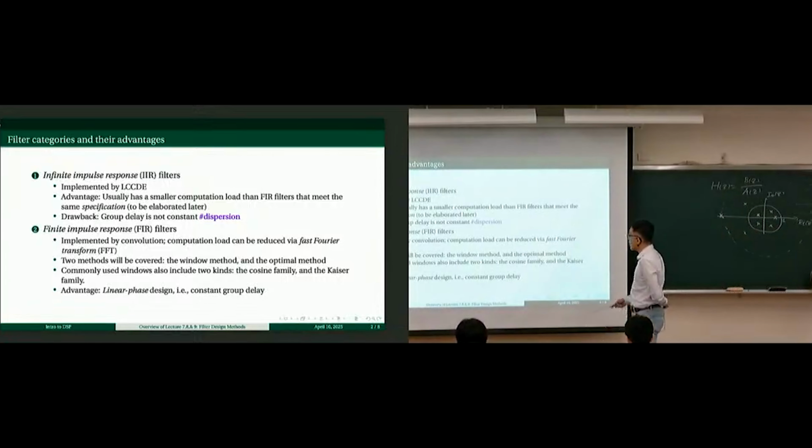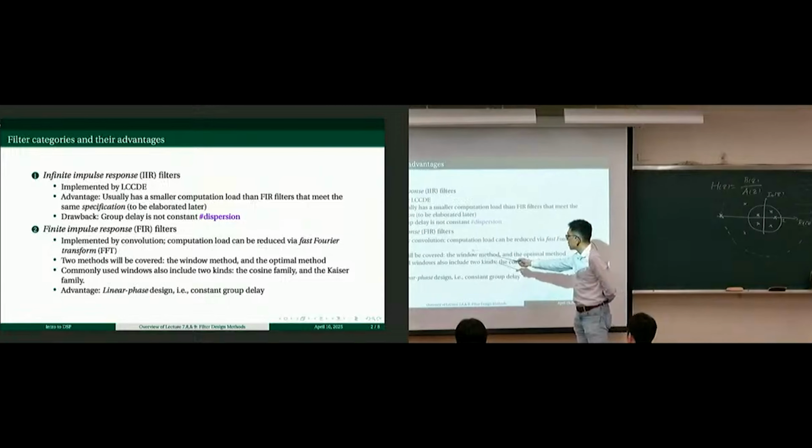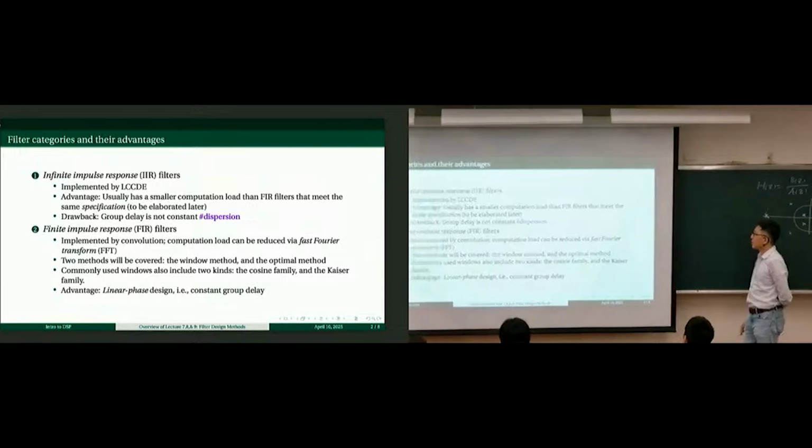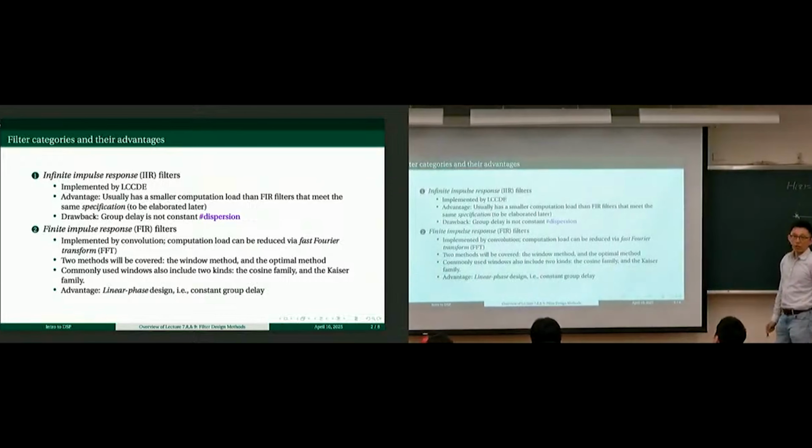But the tricky thing is that FIR, if you implement convolution in the time domain, could be not as efficient as IIR. But you can accelerate convolution by going to the frequency domain through the fast Fourier transform. This is an important point that I'm not sure we have time to address this semester. In my other graduate level course, I talk about that: accelerating FIR filtering by fast Fourier transform, FFT.